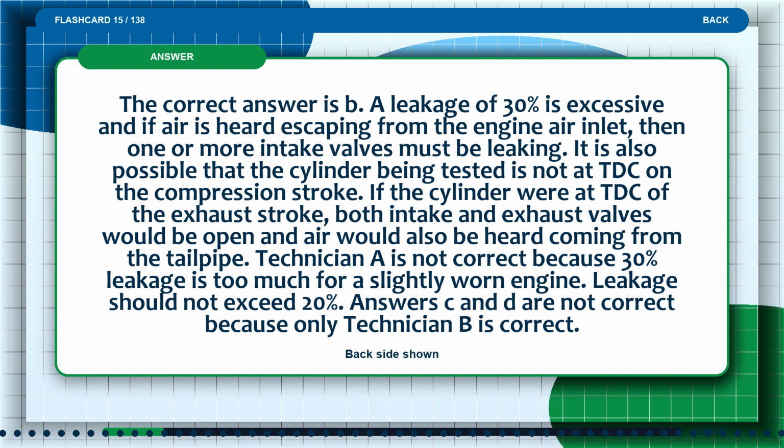Technician A is not correct because 30% leakage is too much for a slightly worn engine. Leakage should not exceed 20%. Answers C and D are not correct because only technician B is correct.